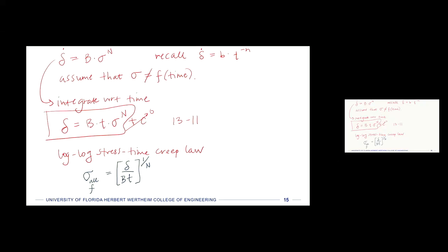So the problem, I'll draw it on the next slide, says, suppose, for example, that it's desired to design a solid circular tension member 5 feet long. It doesn't say the diameter, so I'm just going to assume it's some kind of rod like that. It's 5 feet long, made of 1030 steel, to support a 10,000 pound load. We're going to assume that's tension. So put it as P equals 10,000 pounds for 10 years. So our time, or our duration, is 10 years.